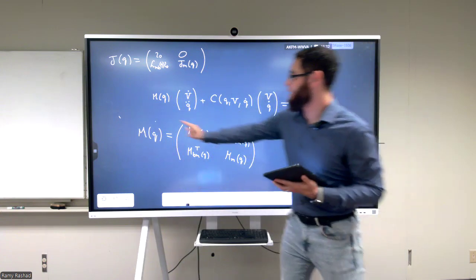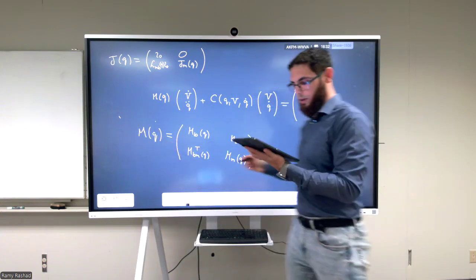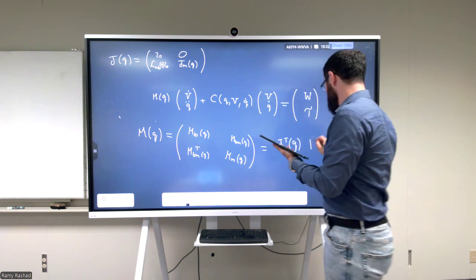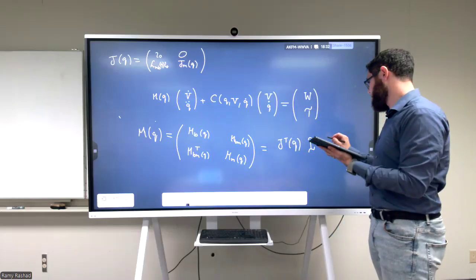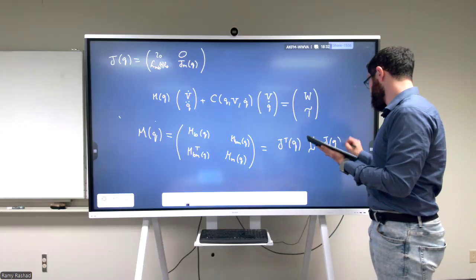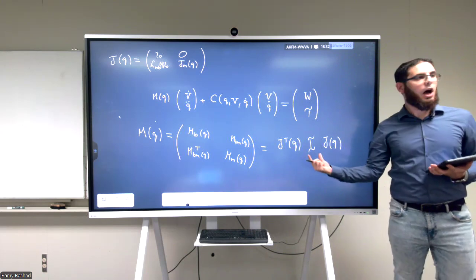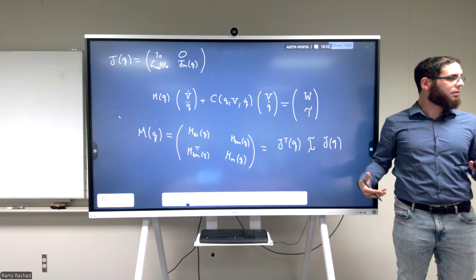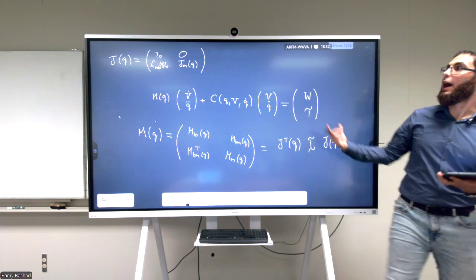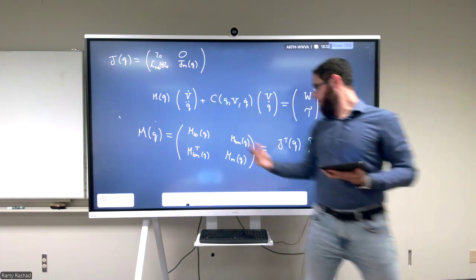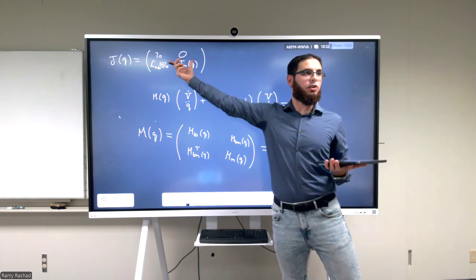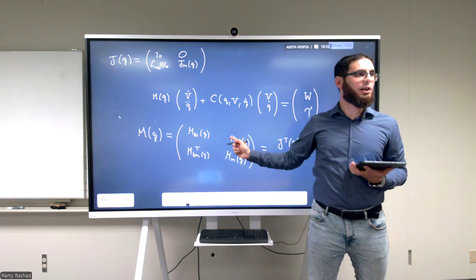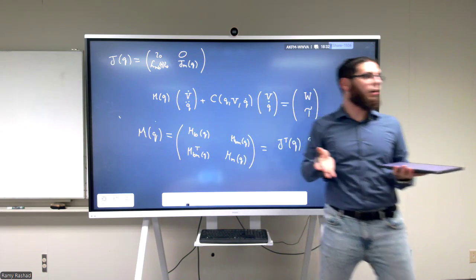Okay. So in the end, where does this M come from? This M in the end is nothing else than the J transpose of Q multiplied by all of the inertia tensors multiplied by J of Q. And you see the I itself had the inertia of the base and also of the N links. The J here, I can decompose it like that. And the J transpose is just the transpose of this. And you see it's trivial to find what all of these expressions are, and I can calculate them in a closed form solution.